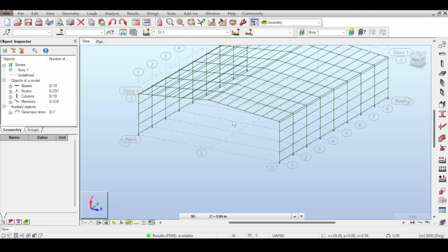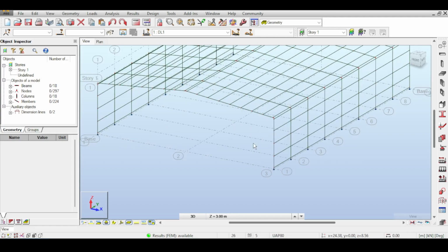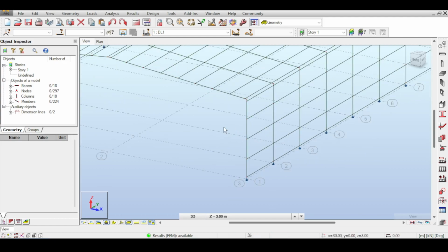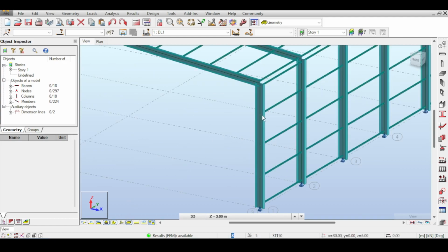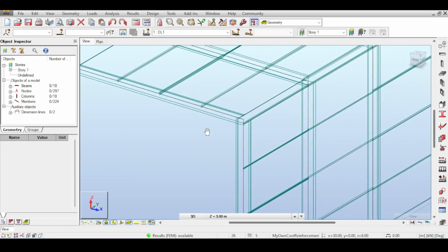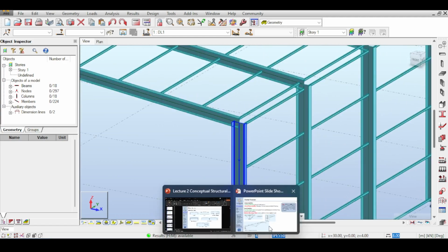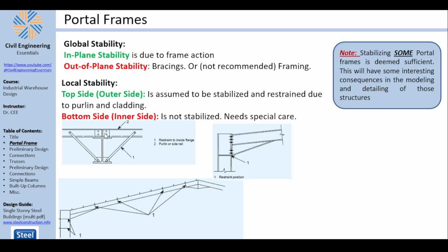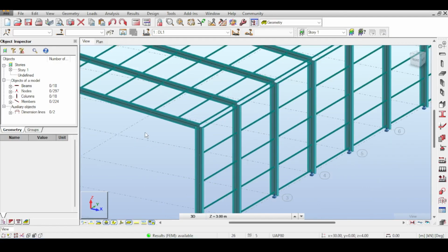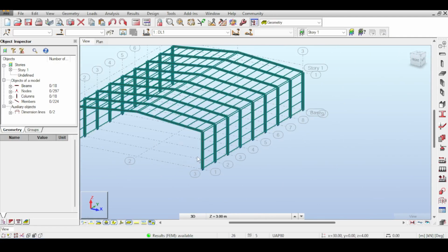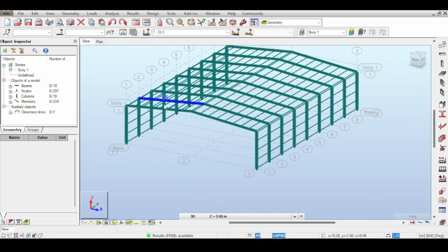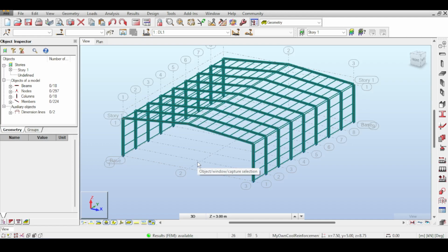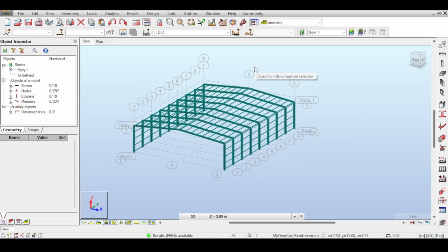At least you need to stabilize the structure. Our plan for the next video is going to be stabilizing our structure, doing some offsets, because yes, purlins are offset, to be honest. They are connected to the upper flange, and I will offset them. So I have to offset the purlins, I have to stabilize the structure, I have to apply claddings, and I have to apply loads. So this is the topic of the next video. So this basically ends my video for today.